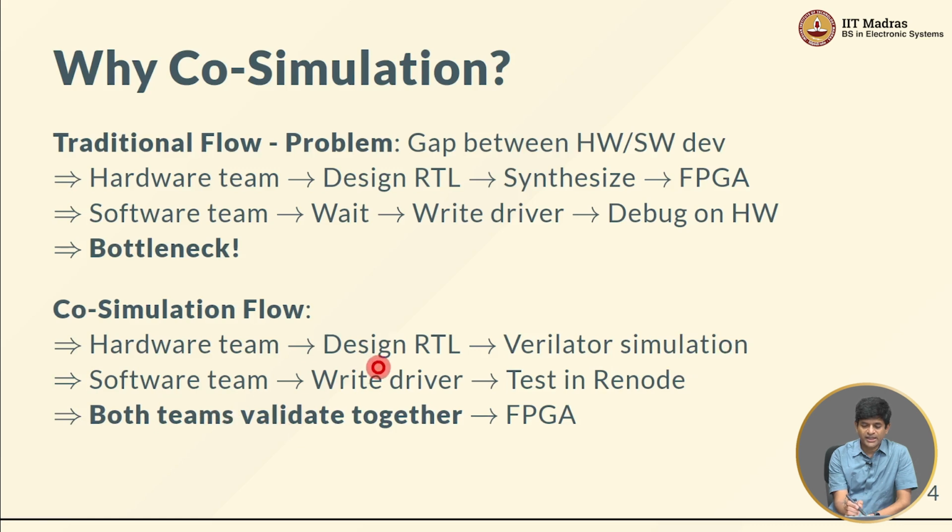Meanwhile, the software team, as soon as the basic specification in terms of registers and so on are frozen, can write a driver. And now interestingly, because of the Verilator simulation, they can now test in a platform like Renode, which allows you to start testing as soon as the hardware team has some Verilog that they believe is on track, right? So even before they do all the synthesis and optimizations and any modifications for speed and so on, the functional simulations and testing can be done more or less in parallel, which means that both teams are able to work more closely together